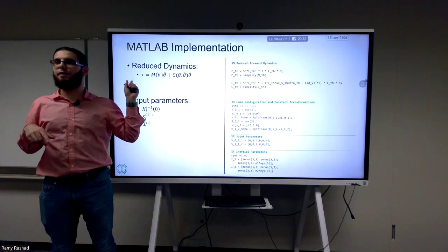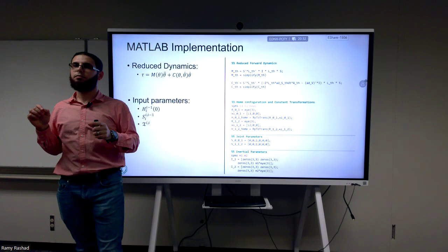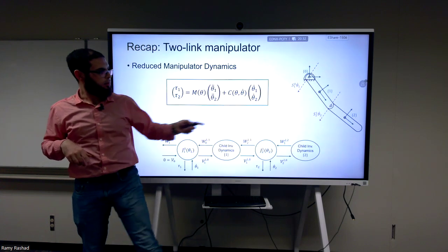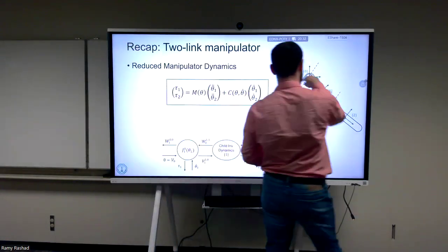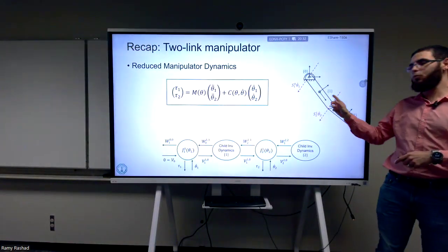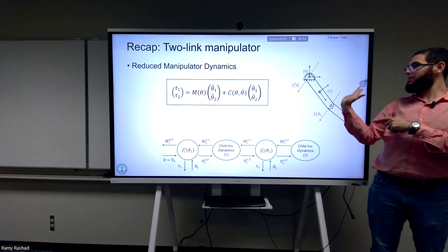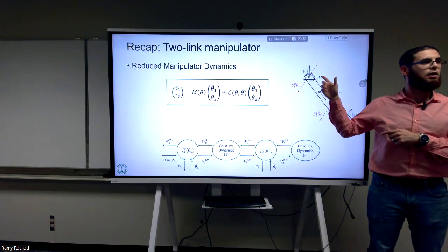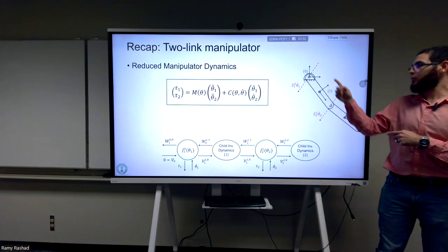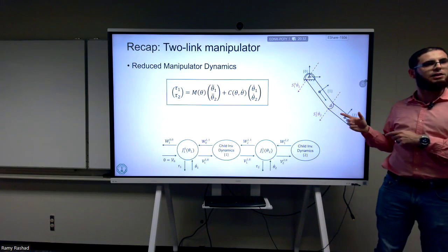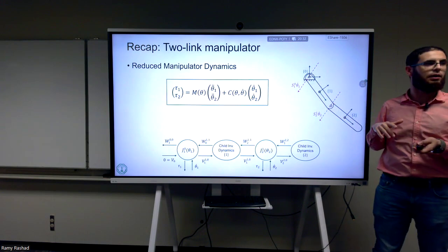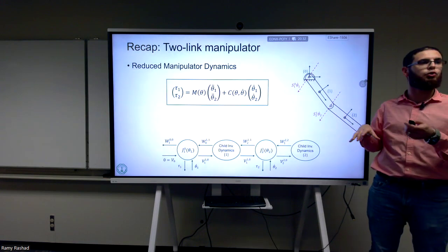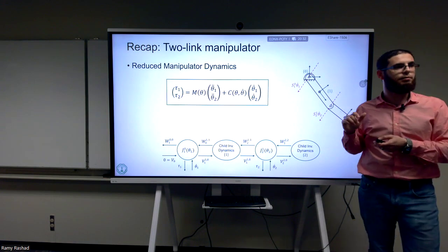If anyone is familiar with what's known as the acrobot, there's a double pendulum that has a motor on the first joint, but no motor on the second joint. So it's a double inverted pendulum where you have only 1 degree of freedom to actuate. But still, it's a 2 degree of freedom system, but only one of them is actuated. So this is an underactuated system. Usually, it's standard when you study underactuated control and so on. This is known as the acrobot. This is like a toy problem for underactuated systems.